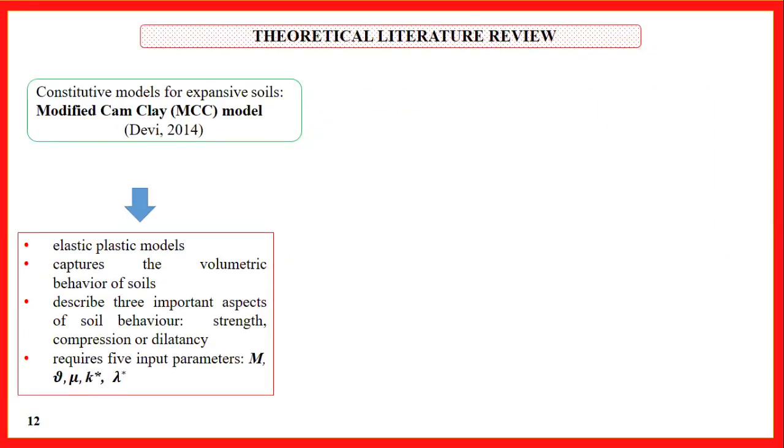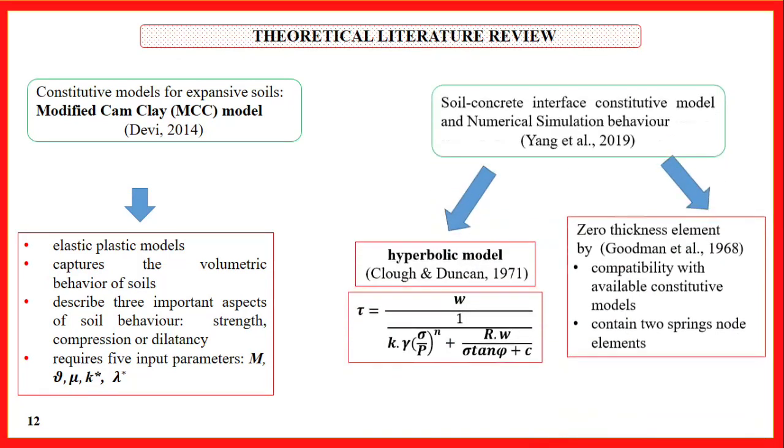There are many constitutive models to describe the expansive soil behavior. The Modified Cam-Clay model is an elastic-plastic model that can capture the volumetric behavior of the soil. It describes the important aspects of soil behavior like strength, compression, or dilatancy. It needs 5 parameters.